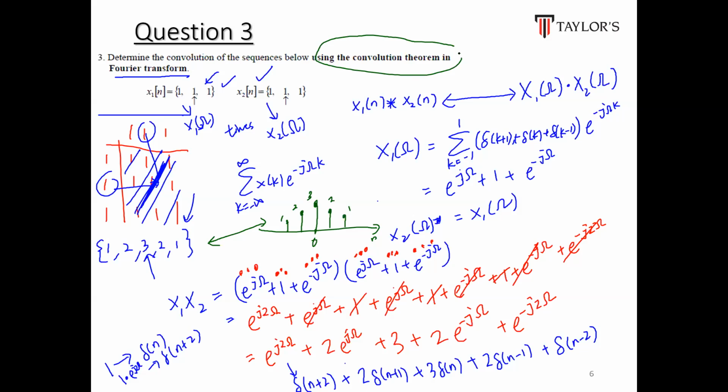For complicated signals, you can do the Fourier transform by referring to the table. Let's say I give you two different signals and ask you to do convolution. After Fourier transform it is a sinc curve, remember? Then you multiply sinc curve by sinc curve, and then you refer to the table to do the inverse Fourier transform again. That is how they do complicated convolutions using the convolution theorem.